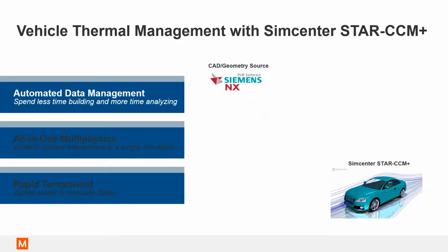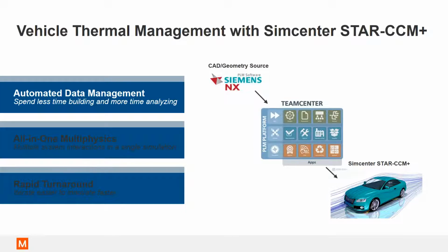However, we can speed up the process of adding material data if we take advantage of the PLM platform like Teamcenter, where the metadata can actually travel with the geometry right from the CAD design stage. Metadata can be managed upstream to help further automate the setup within Star CCM+. Teamcenter is a tool that can be leveraged to help achieve a greater degree of automation, speed, and reliability in setting up simulations.